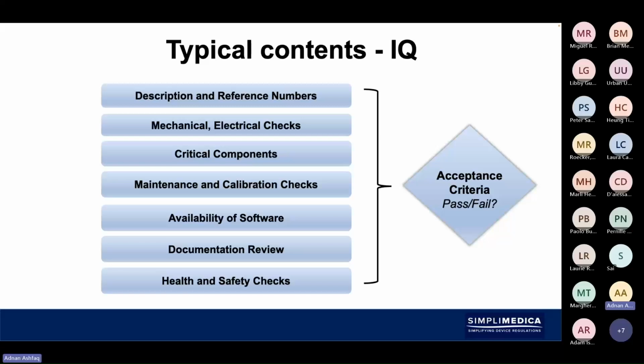So if you're running anything which has pressure that needs compressed air, that can also vary, because you might have air that has to be breathable air, and there are also ISO standards for that, for medical device requirements, where you might be using air to blow onto medical devices to clean them. And I've had that situation before, where we had a Class 3 medical device which was being manufactured in a highly controlled clean room.